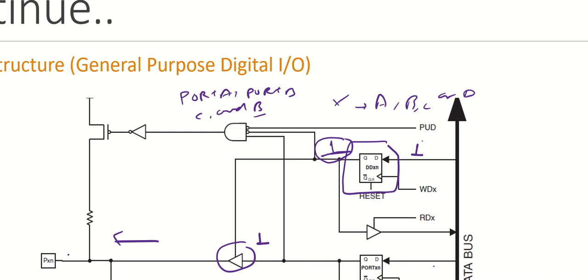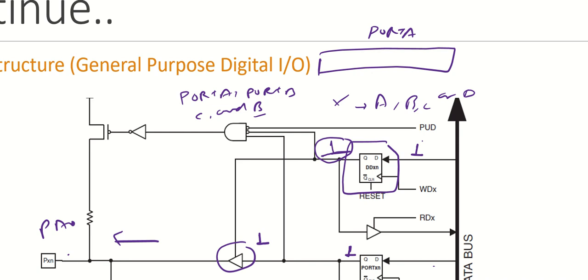on this pin. Okay. So let's say, for example, the port data register contains 1. For example, this is the pin, this is PA0, and port A contains this number. So in the first bit position, let's say we have 1 here. Okay, so this 1 will be available on this pin. So this will be at logic level 1. Okay,